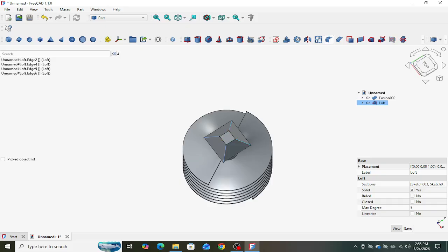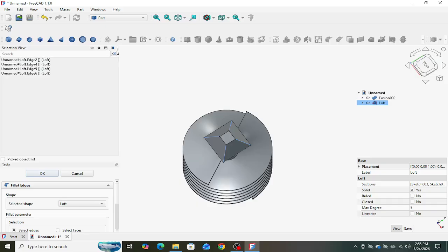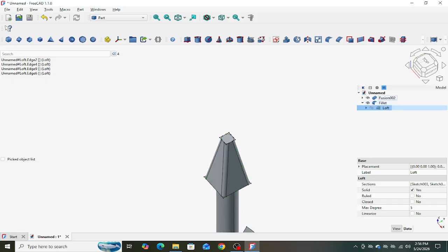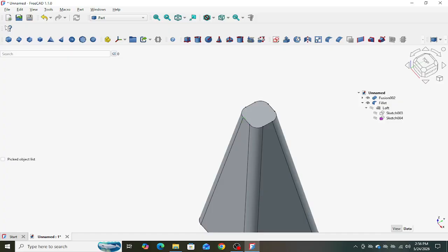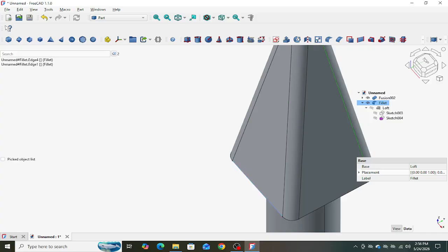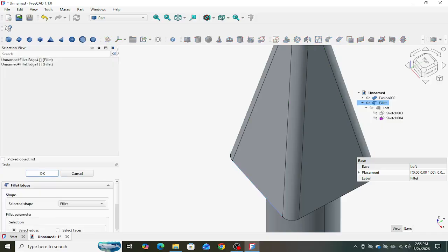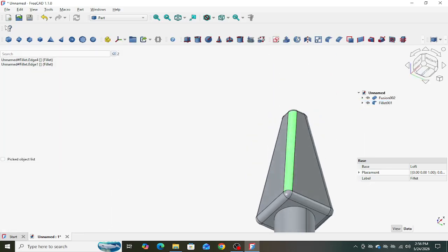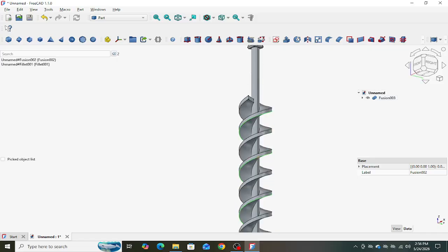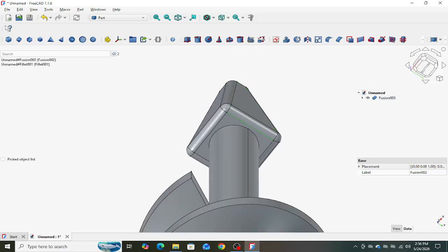Click on those 4 outer edges and fillet them. We're going to hide our sketches. Click on our control select the upper and lower edges now. Fillet them. We're going to be unioning those two together. Make sure that it passes the geometry checks. We'll do that in a second.